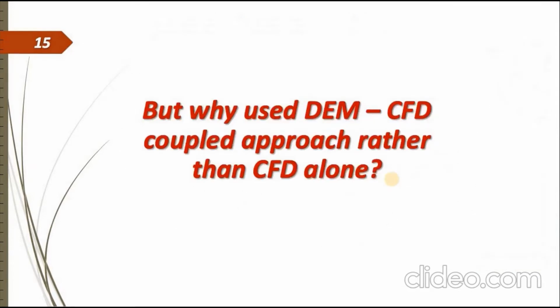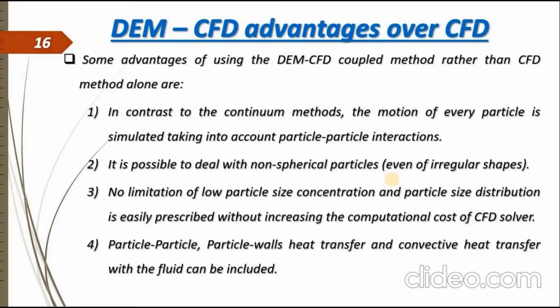Now, why do we use DEM-CFD rather than the CFD approach alone? Let's move towards the advantages. In contrast to the continuum methods, the motion of every particle is simulated taking into account particle-particle interactions in DEM-CFD. And it's possible to deal with non-spherical particles, even of regular or irregular shapes.